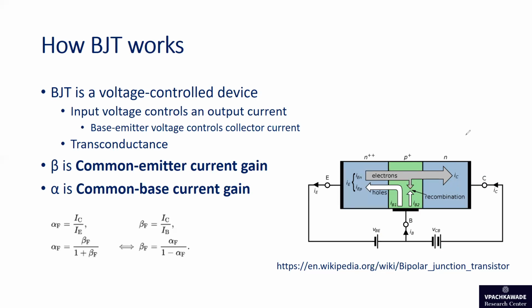Now we have shown the direction of the charged carriers, such as electrons flowing from emitter to the collector, and some of them get lost during the recombination process with the holes in the base region. The white arrows show the component of the hole current in the recombination process. This is the component of the hole current due to the biasing applied.